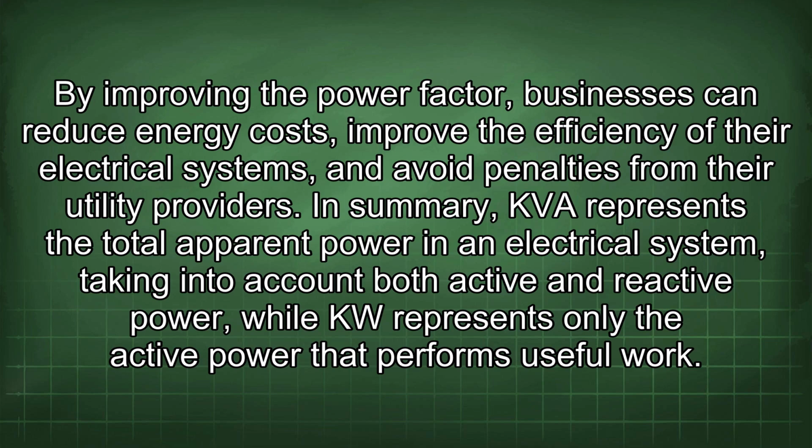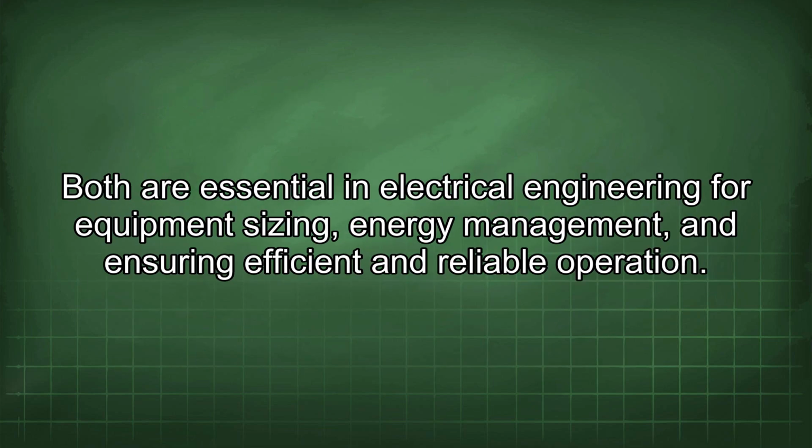In summary, KVA represents the total apparent power in an electrical system, taking into account both active and reactive power, while KW represents only the active power that performs useful work. Both are essential in electrical engineering for equipment sizing, energy management, and ensuring efficient and reliable operation.